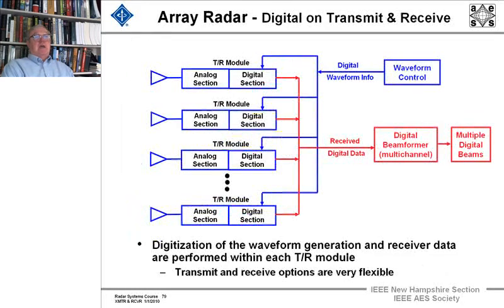And to take it to the final extreme, you can have the entire digital section in each TR module, where we digitally go from the waveform generator right into each TR module to the digital section in it, in blue, for each one, and then have the A to D built into the TR module.